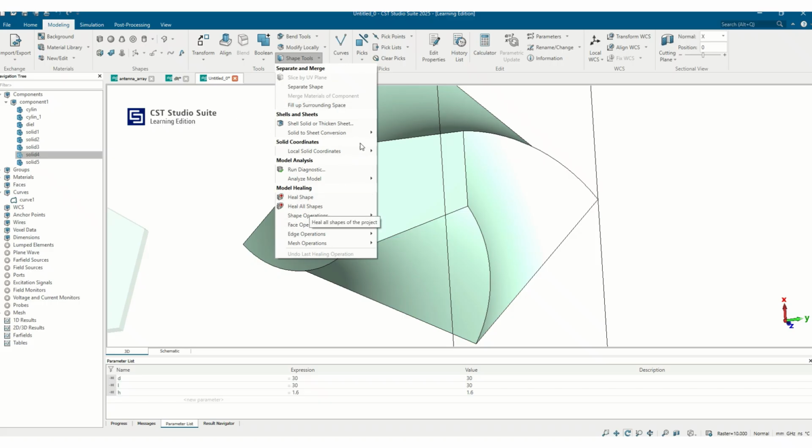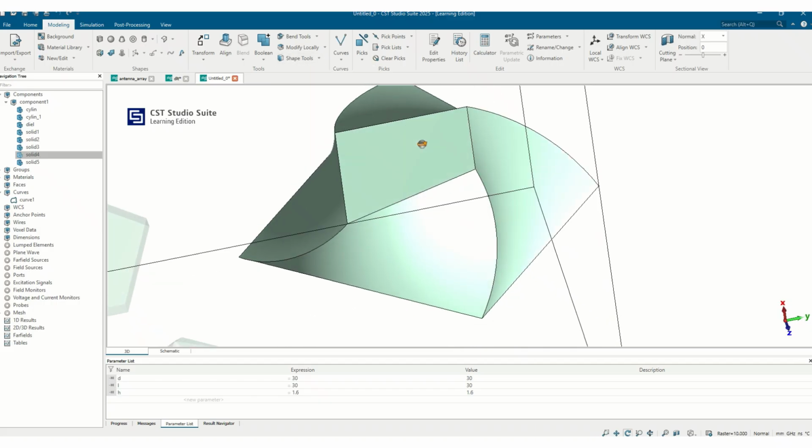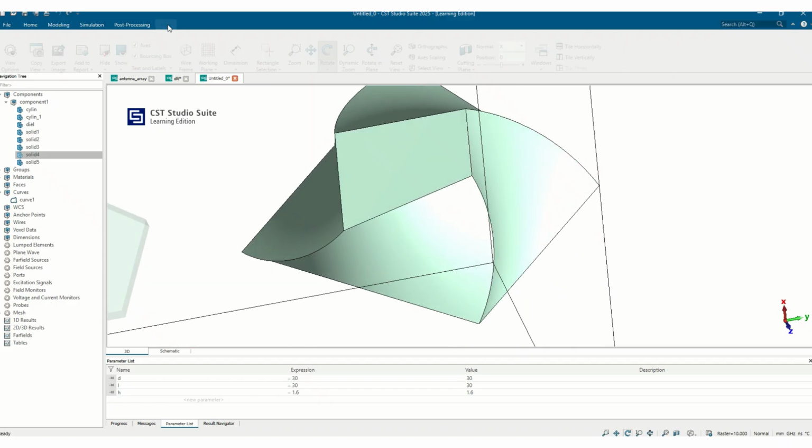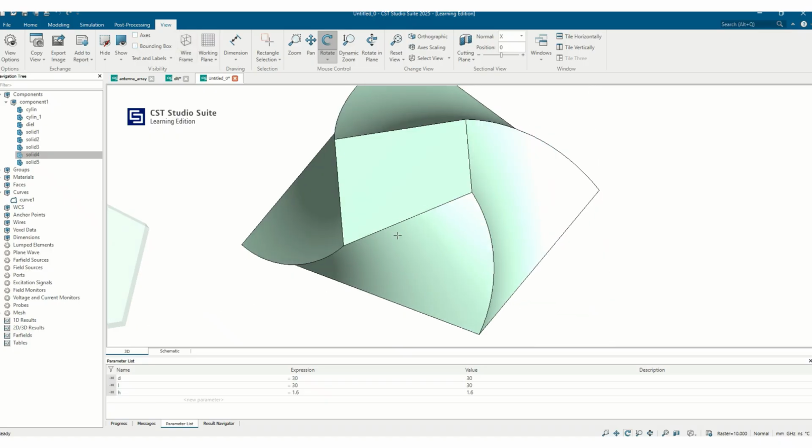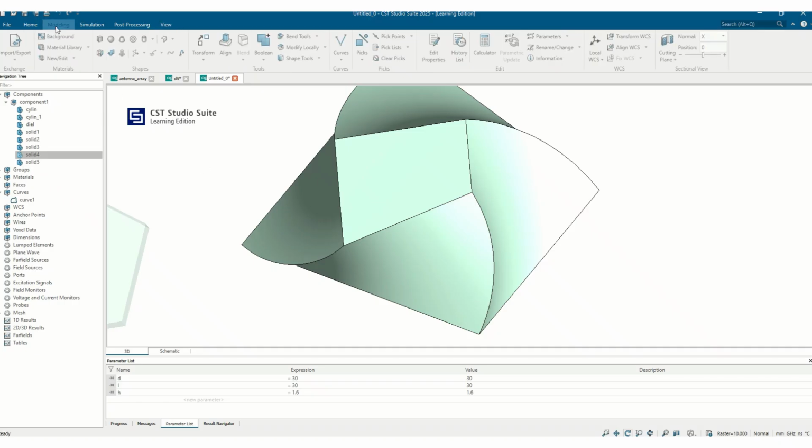Here I would like to show one of the important parameters, slice UV plane. In our previous case, we saw that we have to cut a small part of the CAD model. Let's say I want to cut half of this model. I can go for the local coordinate system. I'm going to select the midpoint of this line. If I click M, it will select the midpoint.